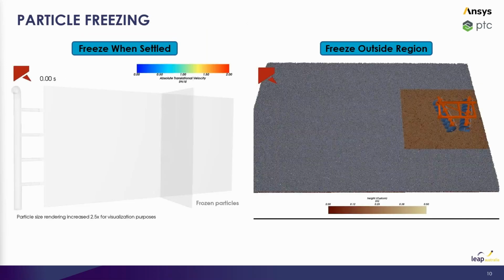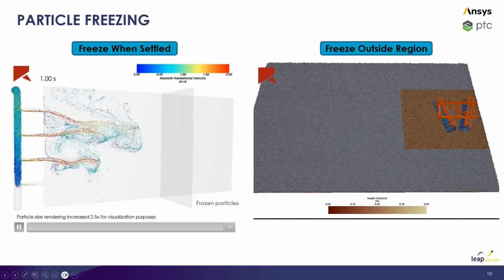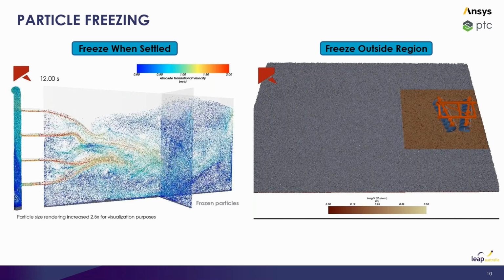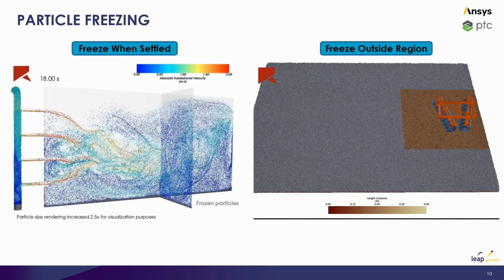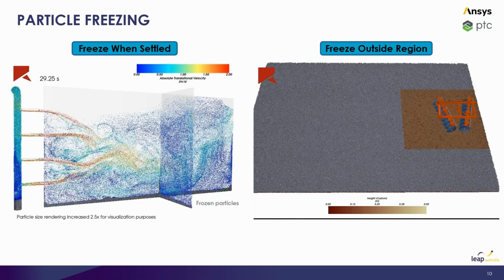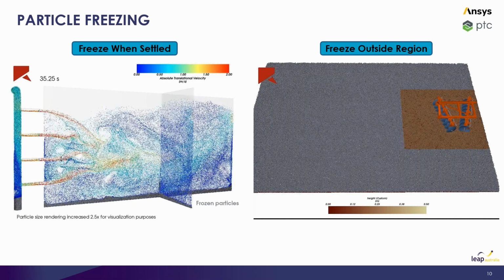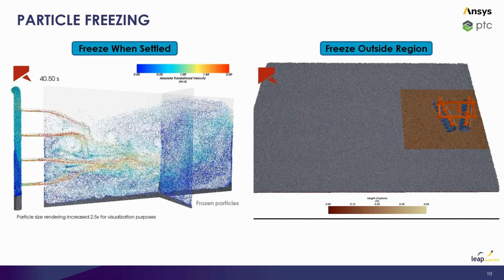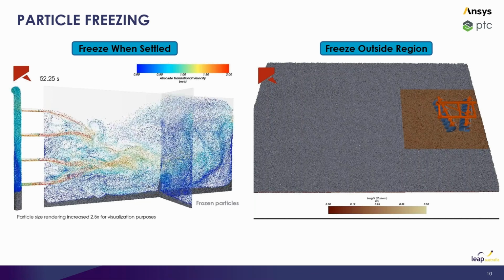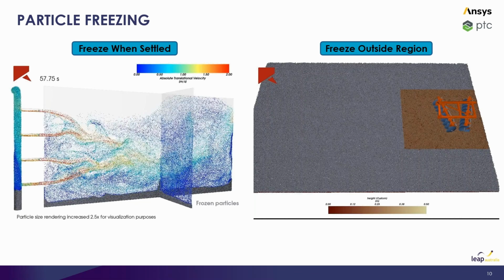Through the Solver API, we could introduce various different conditions which can trigger particles to be frozen or locked in place, effectively switching off motion calculations, while separately, we can also remove particles from contact detection altogether, which you can imagine is going to greatly reduce the computational demand in a given simulation.